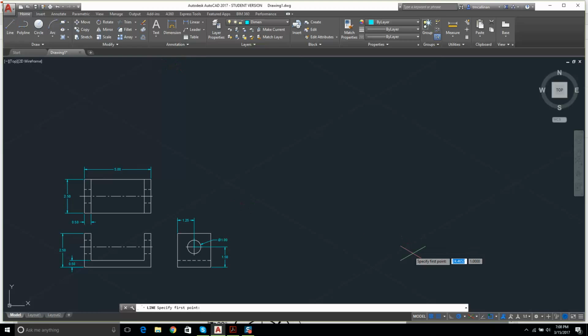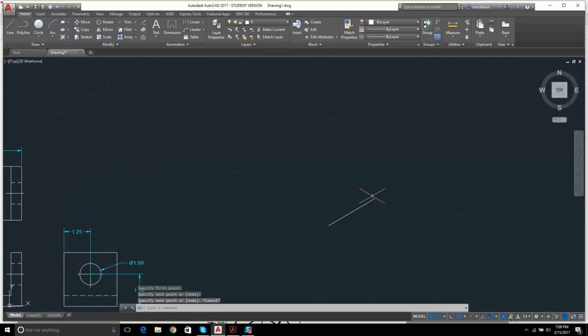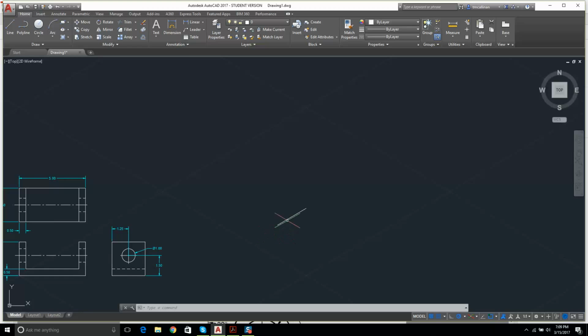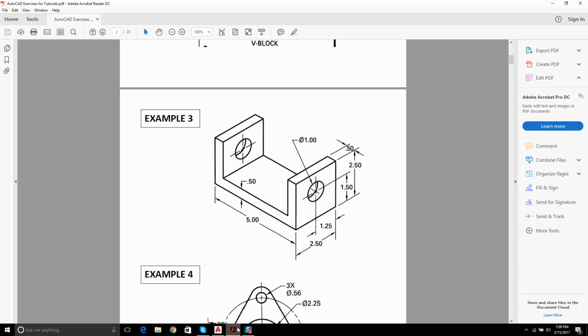I'm going to draw a line from there. Oh, look at this, lovely, lovely, lovely, come on. And let's get in the right layer, 0. And I'm going to draw a line here, and I'm going to come out. Is that the right angle? I need to be at 30 degrees for isometric. Now that's 2.5. How can I explain isometric better? Have you ever tried to draw something in 3D and instinctively you know to draw it at an angle? That isometric angle is 30 degrees. That's still a pretty poor explanation. 2.5. Let's go up here 5.